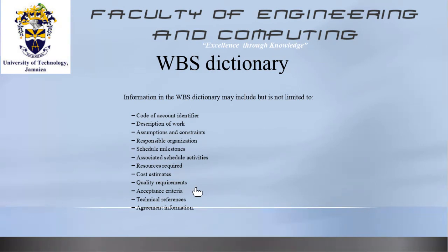What quality? You're buying tiles. I need grade A tiles, right? Not grade C, grade A. You state it. Because when you're doing your cost estimation, you don't want to be getting prices for grade C tiles, but rather prices for grade A tiles. So you have an accurate account of cost to ensure that you don't have any cost overrun on your project.